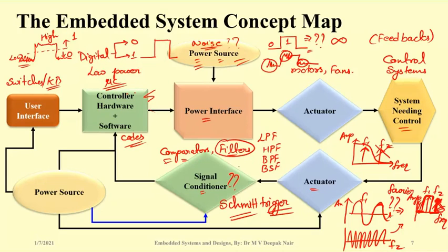Schmitt triggers are just like comparators, but in the comparator you always have zeros and ones, whereas you can switch between lower voltage and higher voltage thresholds using a Schmitt trigger. In a comparator you can only have one voltage level deciding the threshold. In a Schmitt trigger you can have two levels, a lower threshold level and a higher threshold level. Above the higher one it will be 1, and below the lower threshold you will have 0.